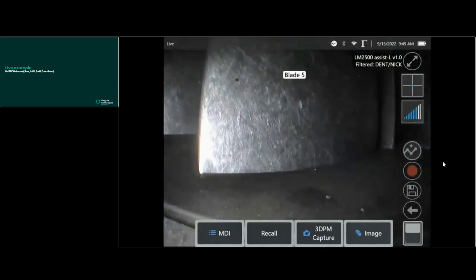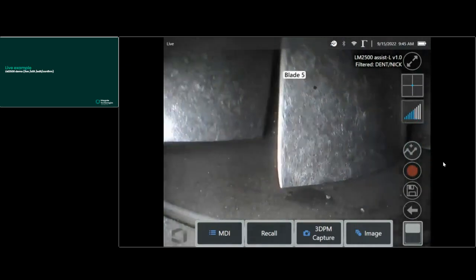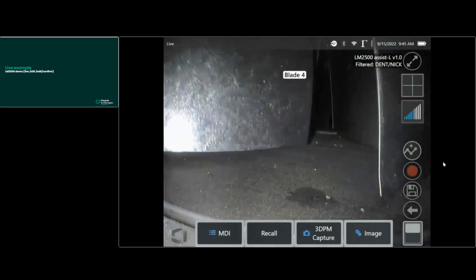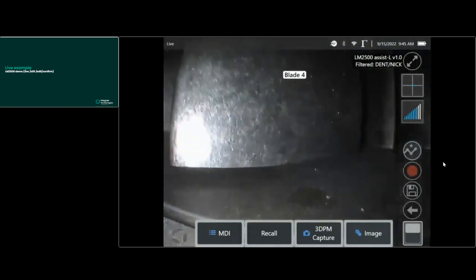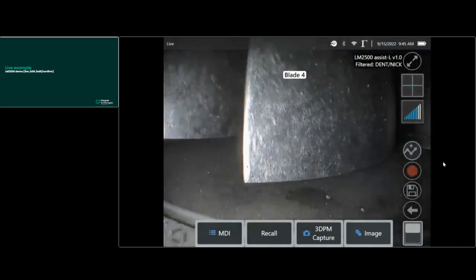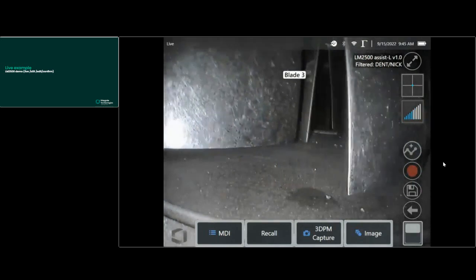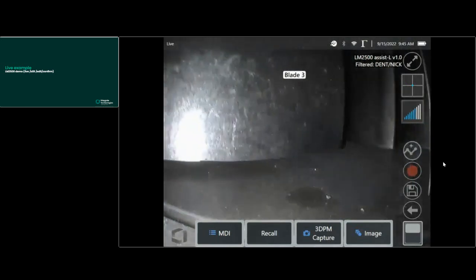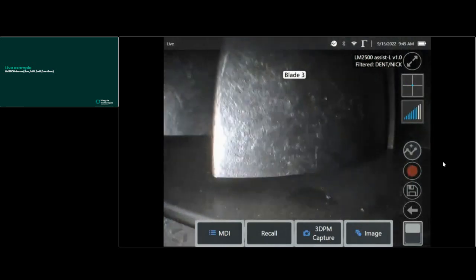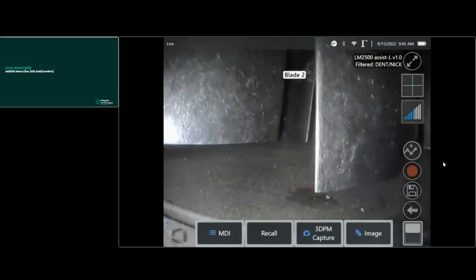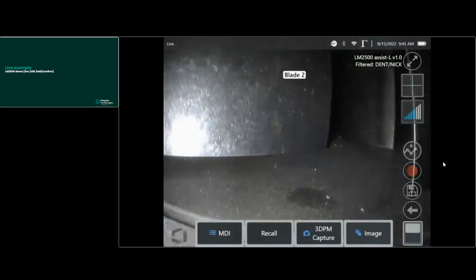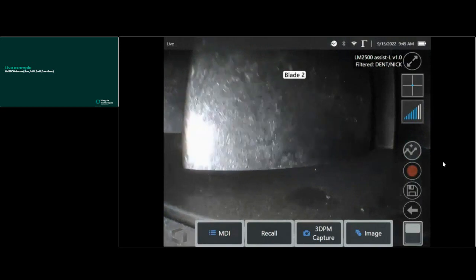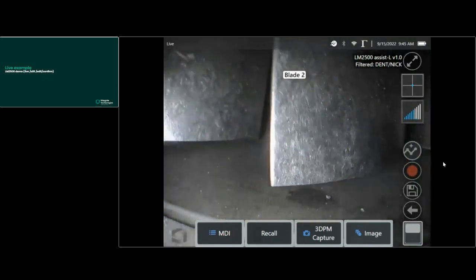If you wanted to filter out one or more of the defect classifications, for instance, what you heard me talk about, TBC loss when you're doing an HP blade inspection, you can not be distracted by all of those bounding boxes associated with that chosen defect type, and just focus on the ones that you are most interested in. Let's just say cracking and tears, for instance.